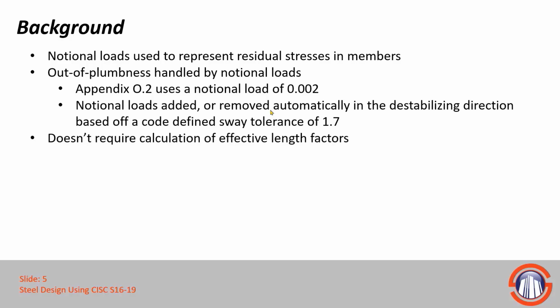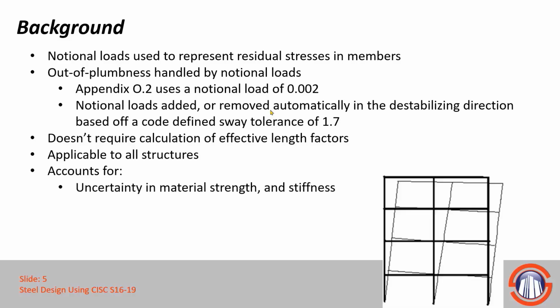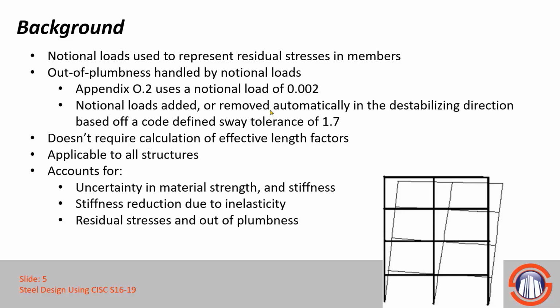One of the advantages of this approach is it doesn't require you to calculate effective length factors and apply those to your members. And for some of the models that we see from our clients, this can certainly be a large time saver. It's also applicable to all structures, making it very well-rounded in terms of its use. And again, as I already mentioned, it accounts for things like uncertainty in material strength and stiffness reduction due to inelasticity, and residual stresses and out-of-plumbness.